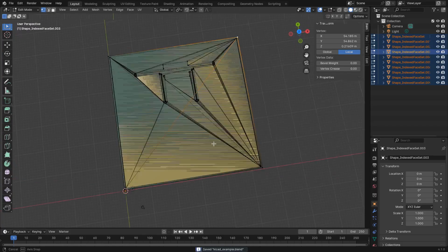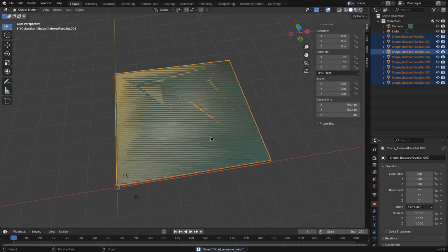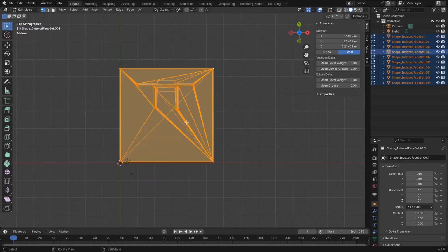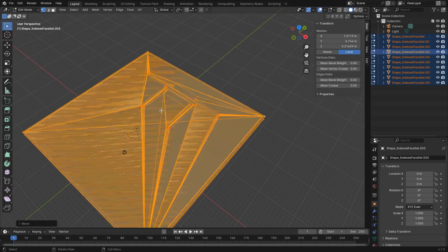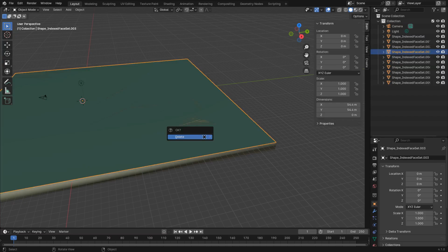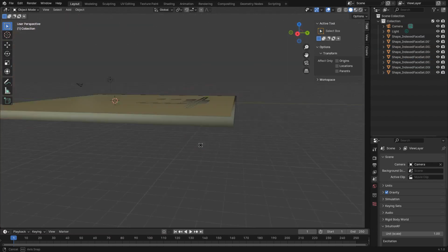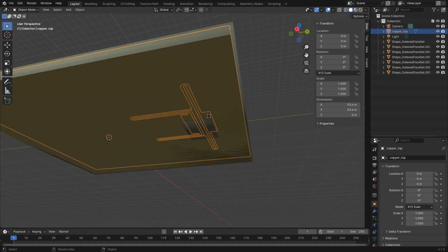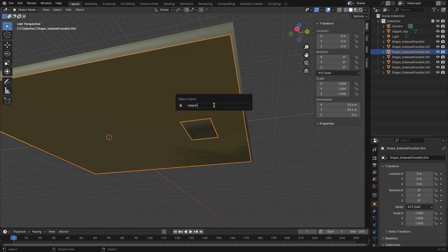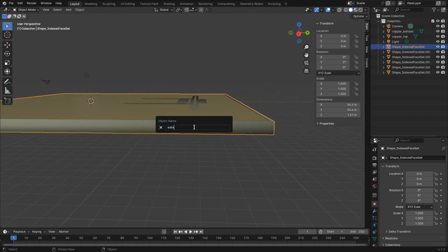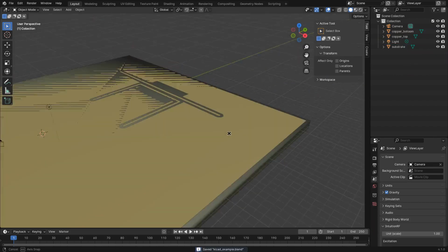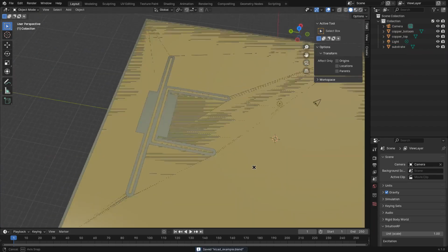Okay. So now we just reapply all transforms again, center it around the origin. We remove everything we are not interested in, like this. And we keep copper top, copper bottom, so substrate, and everything else we remove like this. And now we have our traces.